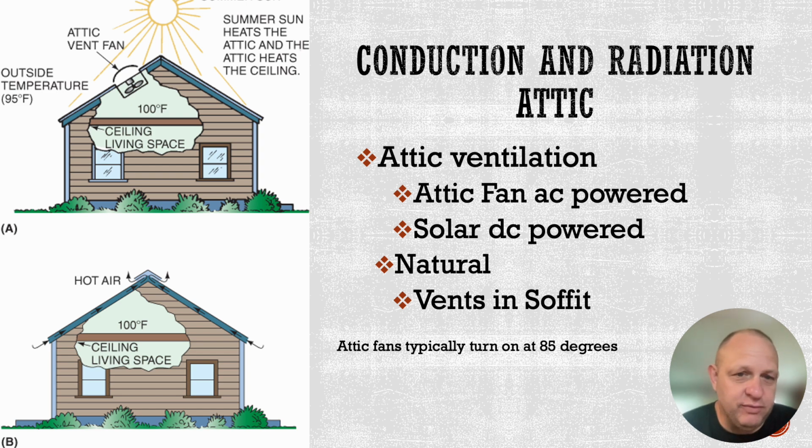So attic ventilation fans are a great way to do it. The diagram on the left shows us an attic ventilation fan right here. But don't just go off and buy an attic ventilation fan and install it. You have to be sure that the place where these fans are located is going to be the most effective in moving the heat from the environment.